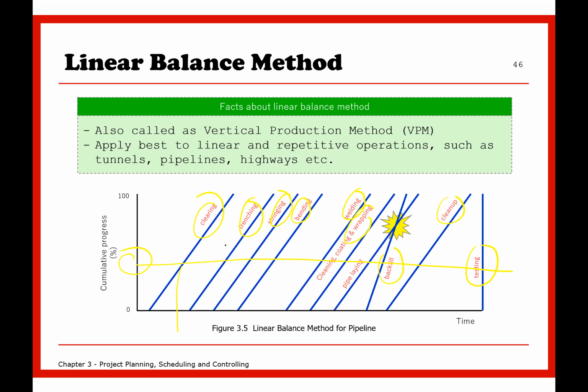When you want to take a look at delay, you have to look at the network diagram, because delay will not be reflected in the LOB diagram. Even a bar chart is perhaps okay, but it is not going to be very clear compared to the network diagram. You see, there is a purpose for each scheduling technique.